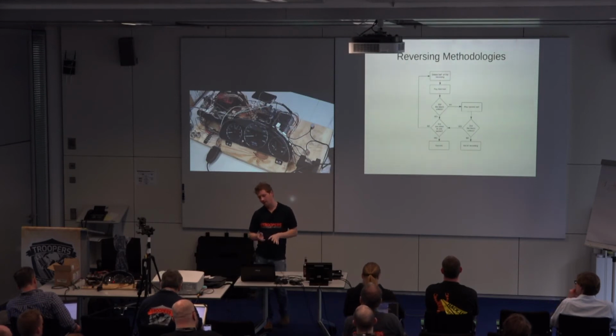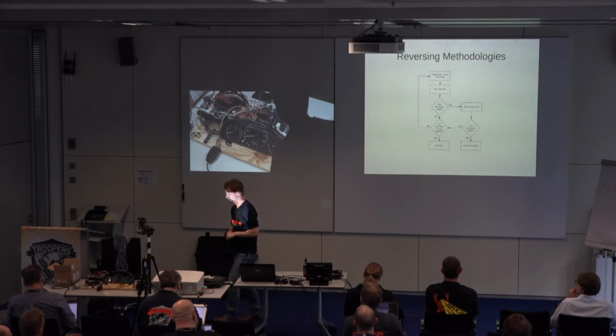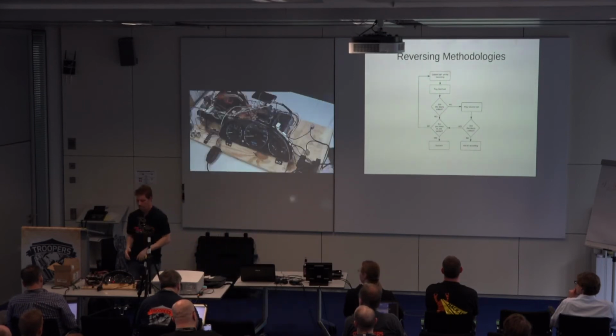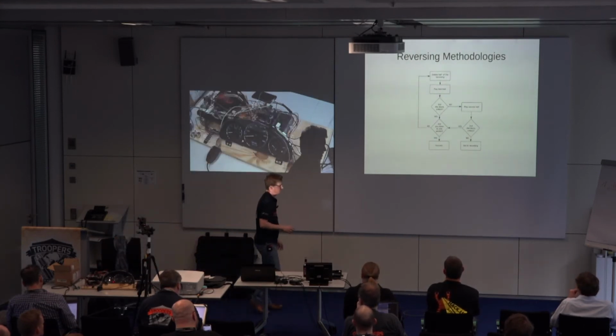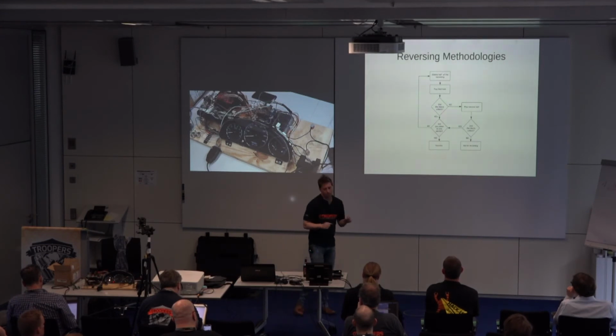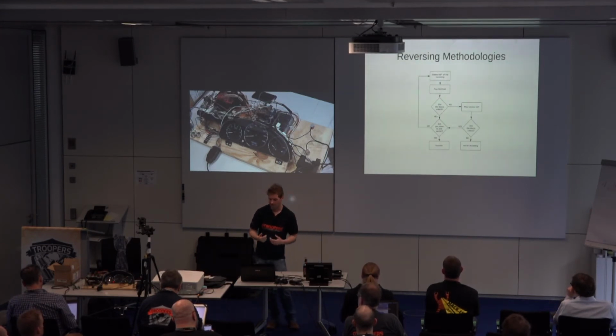What you're going to get a lot of times doing that method is the Christmas tree effect on your instrument cluster. That means all the lights here will usually turn on and blink. It's not a big deal. I guess this would be the more destructive method, but with CAN, it's pretty resilient. Even if you really mess up the car doing this, you just turn off the car, turn it back on, and it resets everything. Not a real big deal.